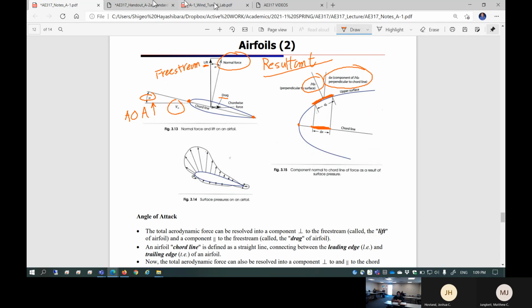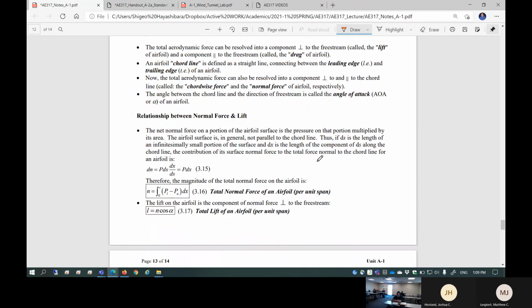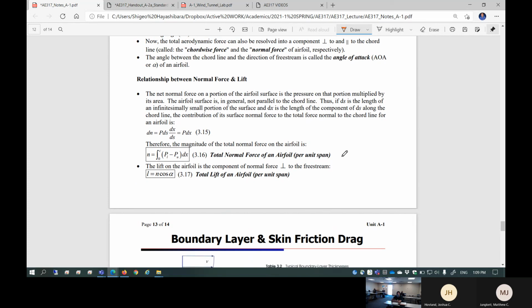Lift. Okay, that's it. Didn't you do a quiz? Do you remember quiz 6? Yeah. Do you want to do it again? No. This is basically a mathematical integration of the pressure distribution over the surface from leading edge to trailing edge to determine lift coefficient. Didn't you do that? It's one of those obnoxious quizzes you hated to death. Very mathematical. Oh, that one. Oh, that one, yes.